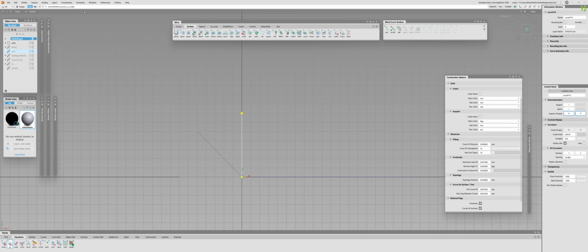As you can see, I need to enter three values for all the axes, X, Y, and Z. If I want to rotate using the rotation tool, I need to hit tab and type 0 for X, 0 for Y, and 45 for Z, and we have 45 degrees. But if I really want to use the subunits, the syntax will be different. So I'll click on rotate, hit tab. The first part is the same, 0, 0, 0, so X, Y, and Z, all of them 0. Once again, we're not working with degrees, we're working with minutes.